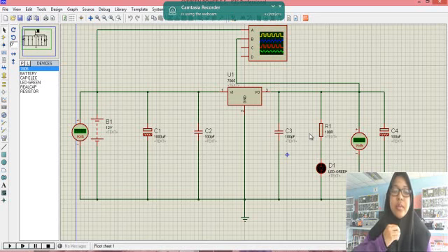So we need an intermediate source or such type of DC power supply to convert the source voltage of 12 volt to the appropriate voltage of 5 volt. So here you can see the circuit that I designed is a 5 volt power supply which will be able to change the voltage level.